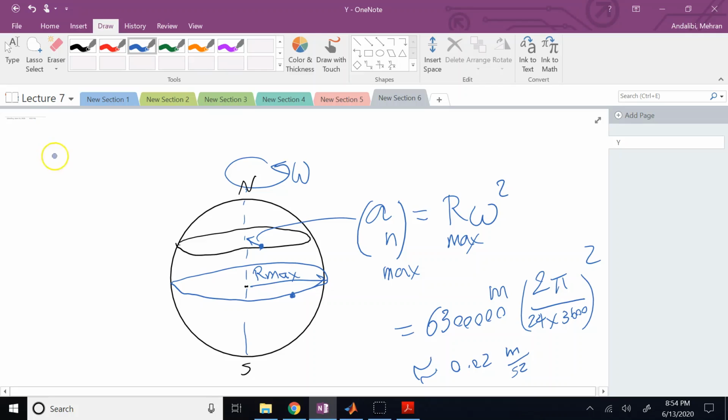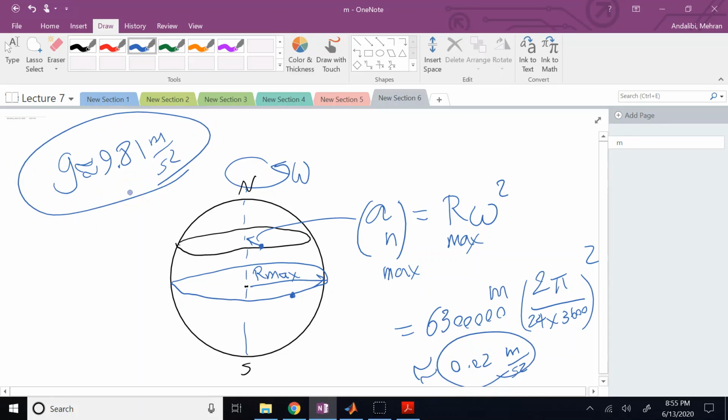But what is the gravity g that most of our daily applications are under? This is 9.81 roughly, right? Depending on the altitude, but something in that order. So you see this number is significantly smaller than gravity. It is less than what? It is less than 0.2% roughly. It's less than 1%. And am I correct? This is 10. 1% of 10 is 0.1, and this is 0.02. Yes. So this is 5 times less than 1% of g. Therefore, it's not really going to do anything. Well, it does, but depending on how much accuracy you need in your application, it might